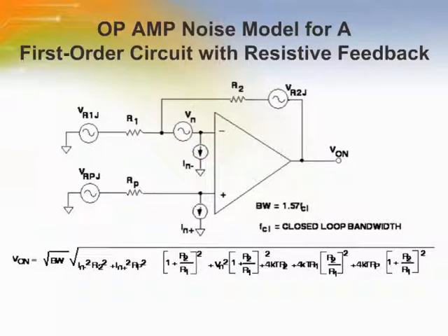This diagram shows the noise sources found in typical op-amp circuits. Each component contributes to the overall noise of the amplifier. Each element's noise contribution is calculated, then root sum squared. It is easy to see the contribution that resistors make, and hence why low values should be used. The noise current multiplied by the resistors creates a noise voltage. The total noise calculation is referred to the output, or RTO. If you wanted to figure out the input referred noise, you would need to divide by the gain of the amplifier.